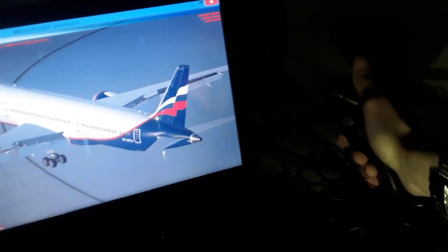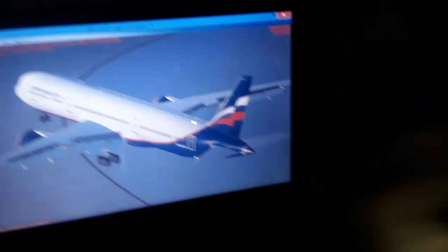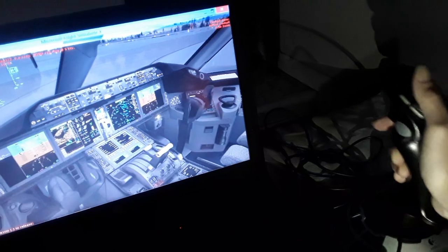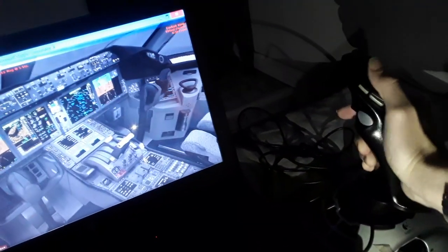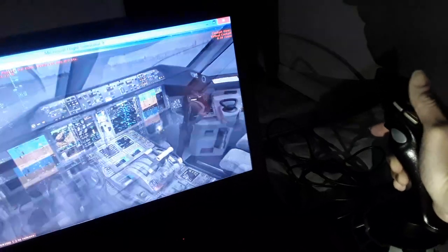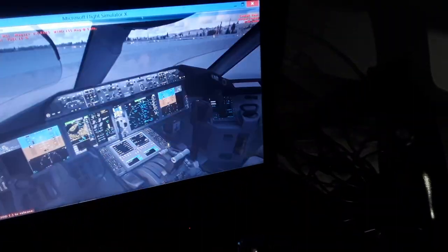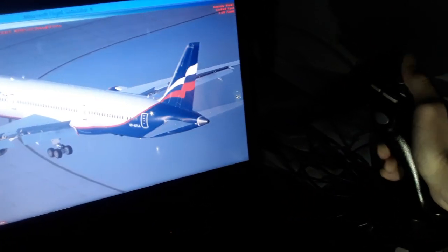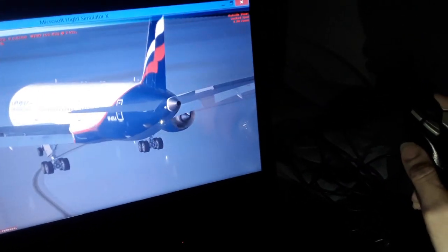We have also the elevator, the pitch axis. So the elevator is here, as you can see, this column is the elevator for climb and descent. Very simple. So this is the pitch axis or lateral axis from wingtip to wingtip over here. From one wingtip to the other, it transverses also the center of gravity. You can make the aircraft pitch up or pitch down. We have also the horizontal trim stabilizer as we fly. So you can descend, you can climb.